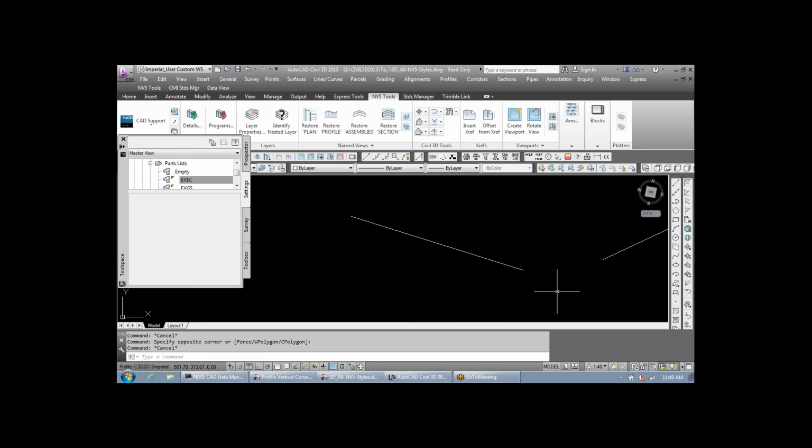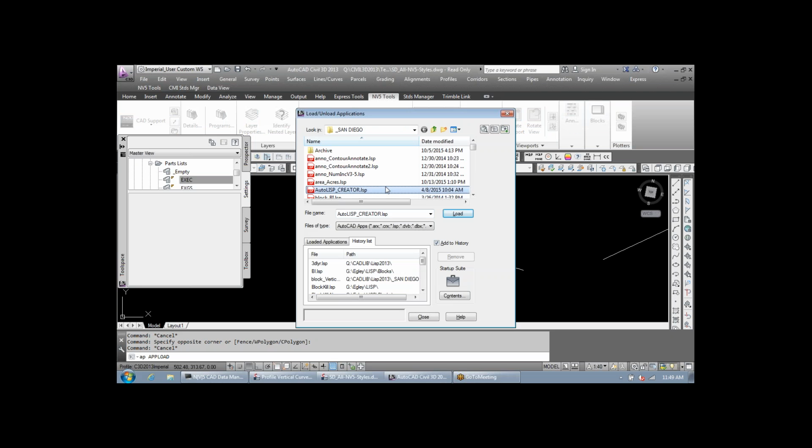Next one that's very helpful and can have some really good applications for both T&D and gas is to measure an angle between two lines with a vertical exaggeration. So let's say on our profile we have an exaggeration of 5. It's really hard to find what angle that grade break is in our pipe because it has a vertical exaggeration. So what you'd end up doing is you'd actually develop a block, do all kinds of workarounds. There's now a LISP routine to measure that for you.